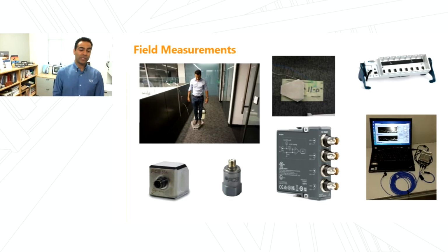So what do we do for the field measurements? We usually do either forced or free vibration measurements. We have different ways to input these vibrations that we will go through. But we use accelerometers to mainly collect the vibration data. These accelerometers are then connected to data acquisition systems. And then we have proprietary software that records and processes that data in real time and allows us to also do post-processing of the vibration data to understand the vibration characteristics of the floor.